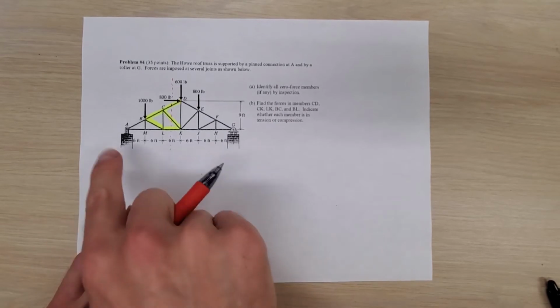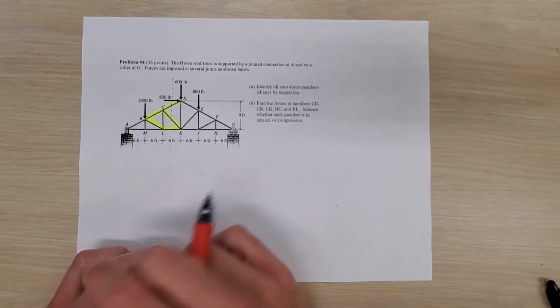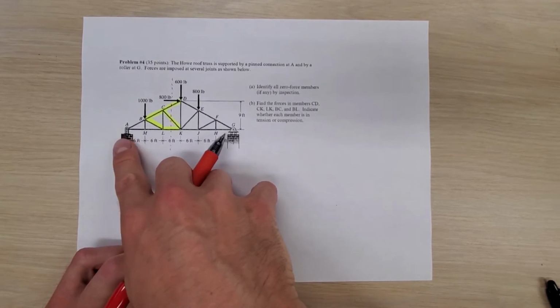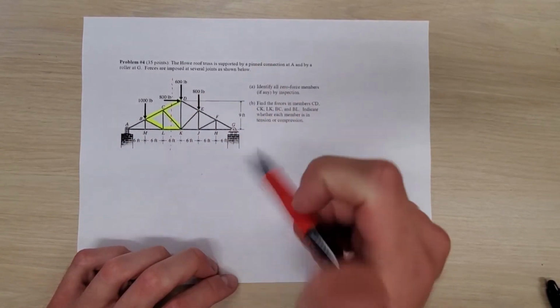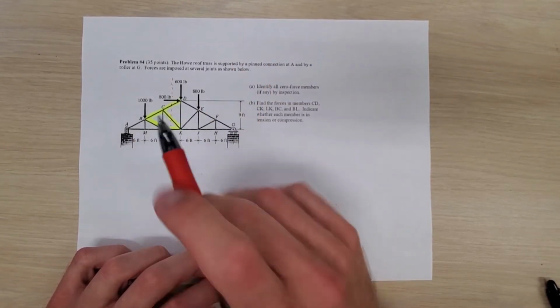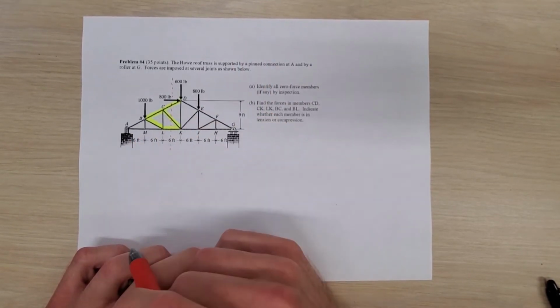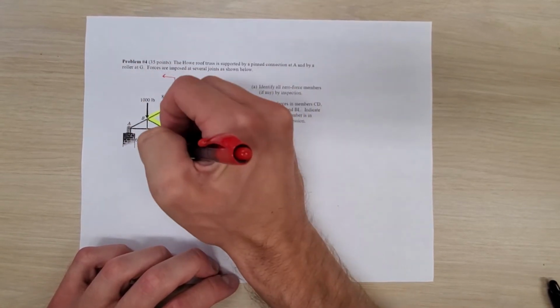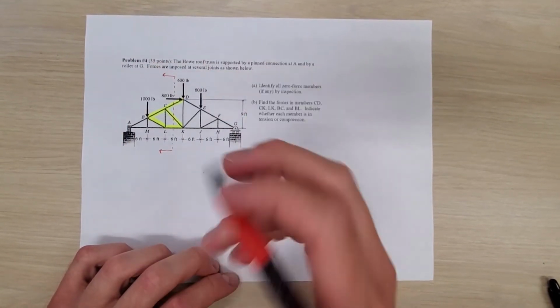Because we're not given the reaction forces in this problem, which sometimes on an exam you are, I'm going to decide to look left, because there are only 3 things over there, and we have only 1 x-force. As a result, I think it'll be pretty easy to look to the left and solve everything from there. So I'm going to draw my arrows over this way, and I'm going to look left.